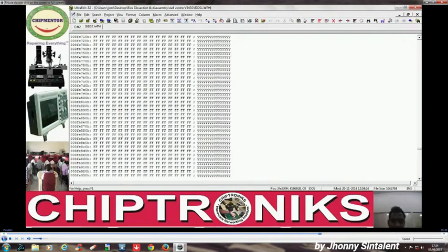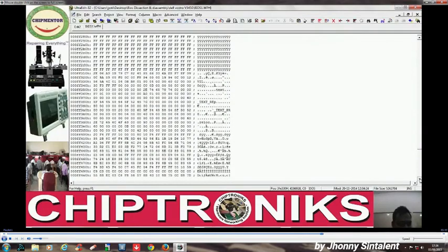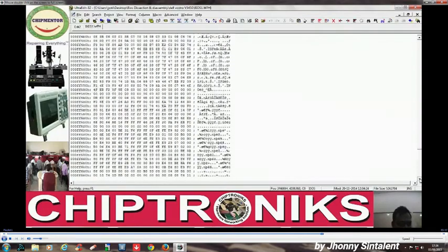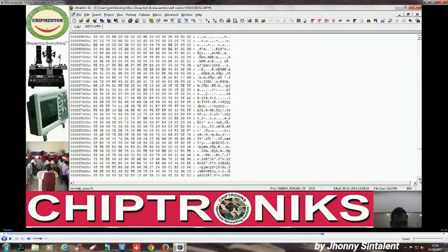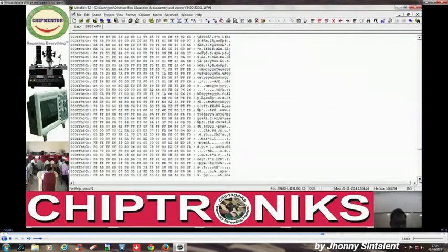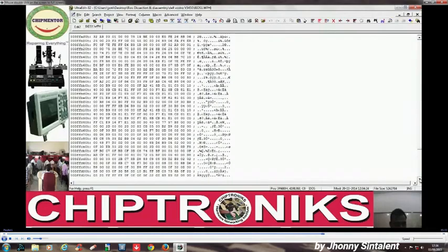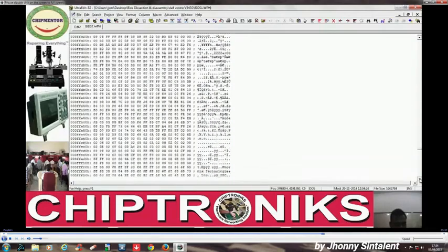so we have to do something with our BIOS backup of the chip. All right, let us first do our step. We have to extract the first 4 MB for the system BIOS, the rest is for the EC BIOS. So we'll go to 3FF.